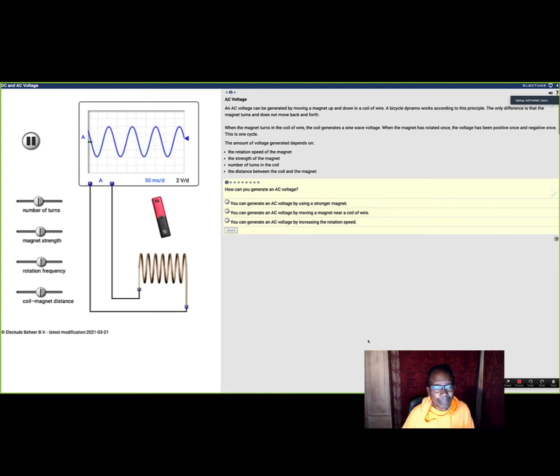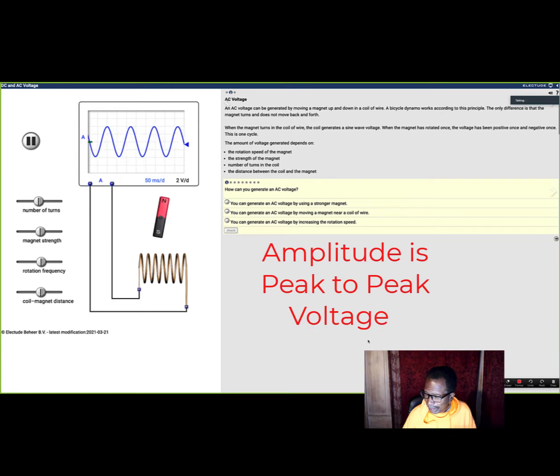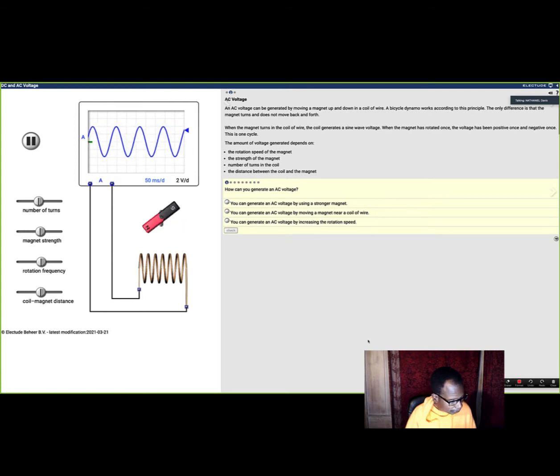Yeah, you could do it with a lab scope and a set of cursors. But one of the main things on this one, I'd be more concerned about the amplitude, the height. Because if that magnet is weak, the amplitude is going to be small, and that can cause a problem. Okay, but my question is whether we can also call it frequency, or whether frequency is just applied to digital signals.